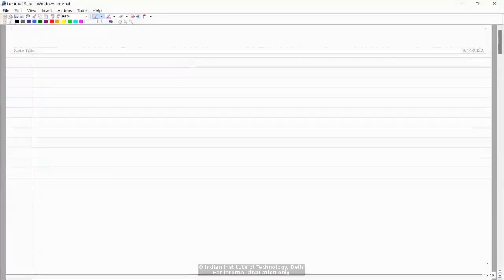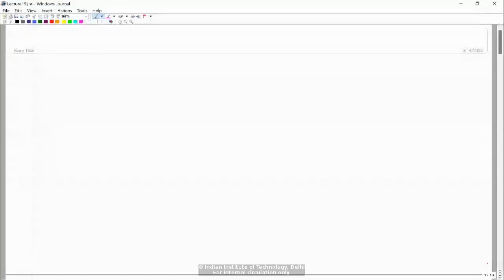So last class we discussed the plane stress, plane strain element, basically a three-noded triangular element. Today I am going to talk about the four-noded rectangular element and then a general quadrilateral. To satisfy the compatibility, we have to do the formulation in natural coordinate space. That is what I will discuss today.